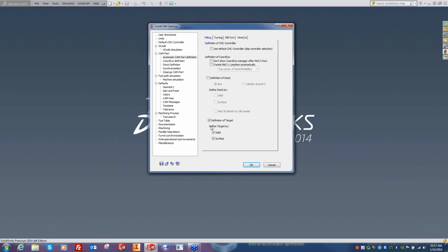The problem with that is, it's not really a problem, it requires an extra step for you to update any of the parts inside the assembly if you decide to work on them and then you get a revision on one of those, because then it would require you to copy that part and drop it into the folder. So it would require action on your part. If you're in single part mode, which is 99% of the people, then it automatically updates because it's made a copy of that one part and puts your original part away for safekeeping.